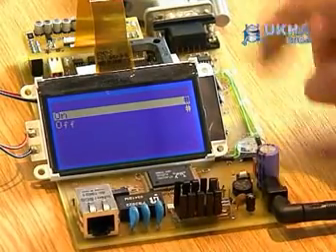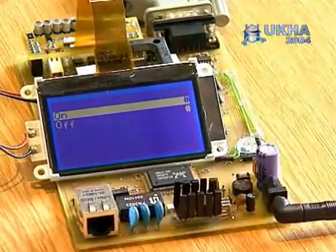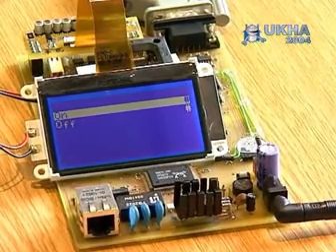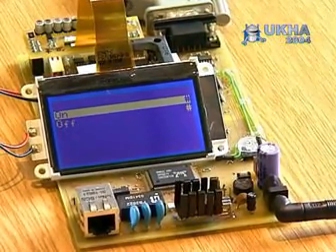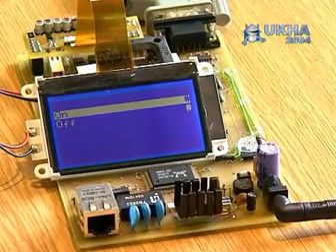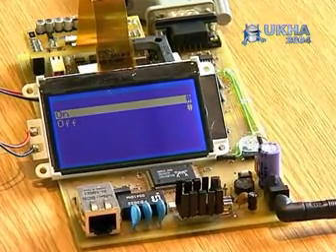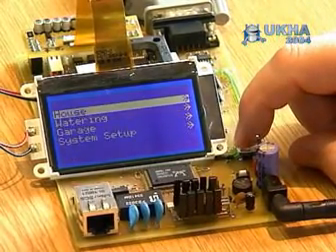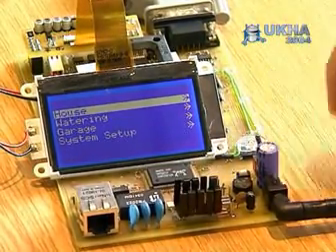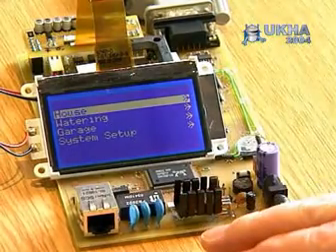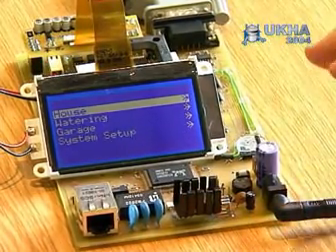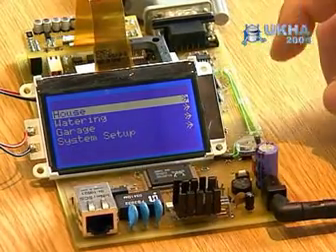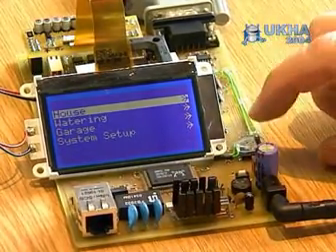You press the button and it sends a message out of Ethernet off to whatever is at the other end, which will turn the text-based request into an action. For example, sending an X10 signal to turn the light off. The menus are defined on the PC. In the future they'll be downloaded by the Ethernet interface, but just because it's an early prototype, they're currently coming down the serial port. And we can actually update them literally as you see it.